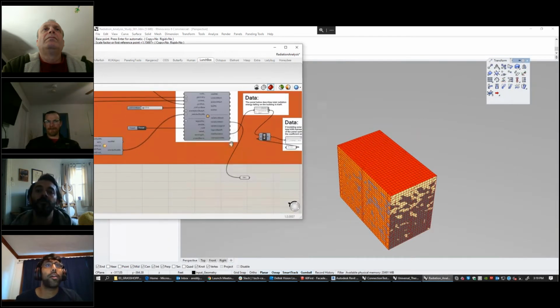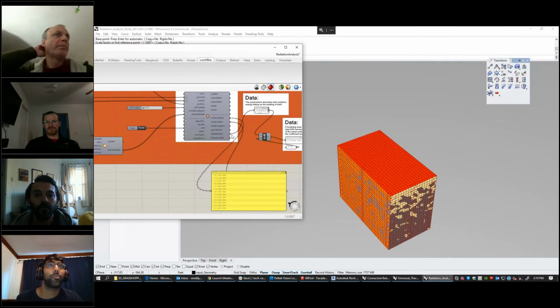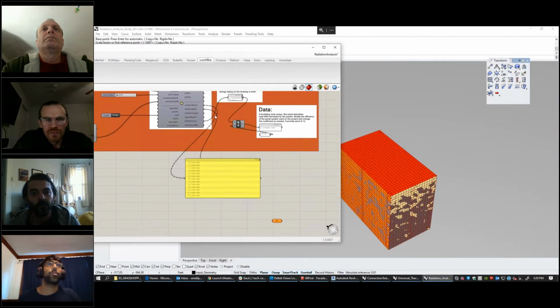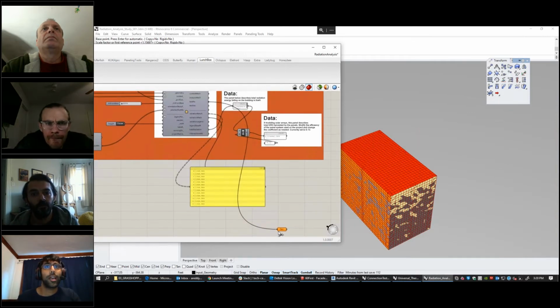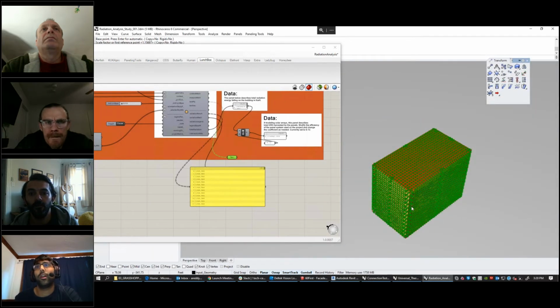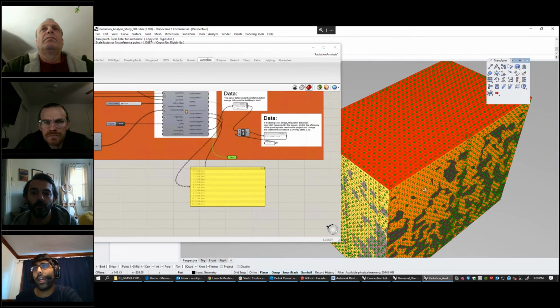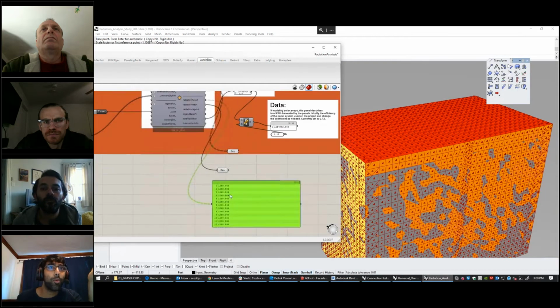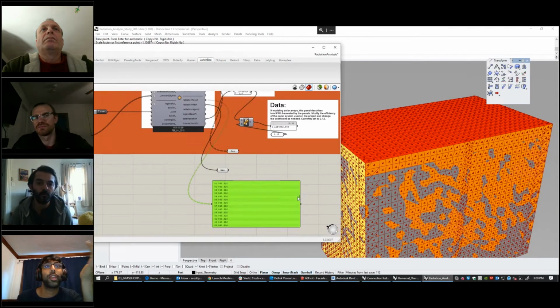But then we also have a result, which if I use panels and really look at it, is giving us kilowatt values at specific points. If you go to test points here, you'll also be able to see the points of the analysis. So let's get a geometry component and tease out all these test points. It's testing at each single one of these points, what is the radiation value, and then it's making a tile, and that defines the color of the tile. For each one of these points, it's just a numerical value for the kilowatt hours.